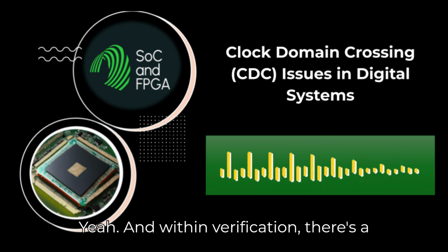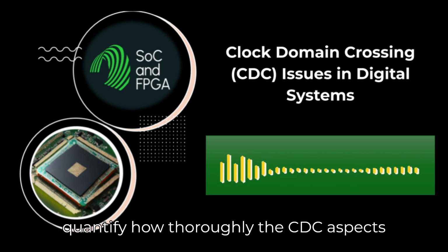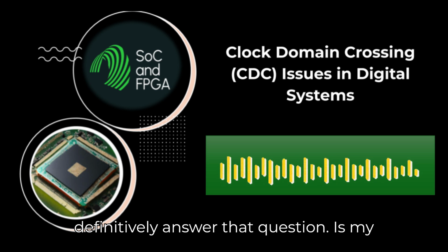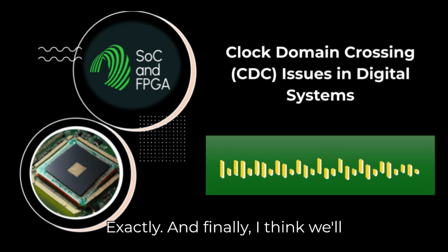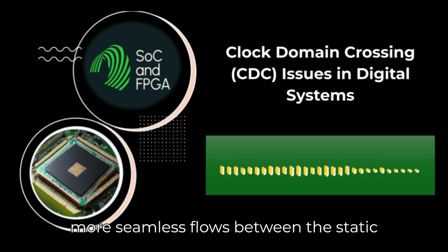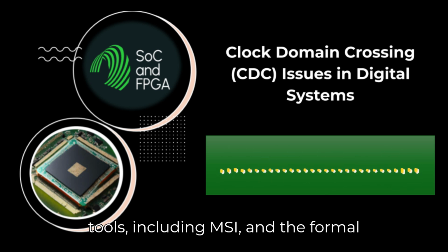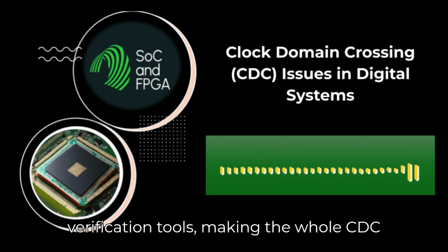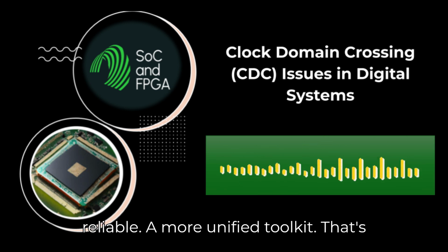And within verification, there's a push for more comprehensive coverage models, better metrics to actually quantify how thoroughly the CDC aspects have been verified, trying to definitively answer that question: is my CDC verification done? Moving beyond just bug hunting to proving coverage. Exactly. And finally, I think we'll continue to see tighter tool integration, more seamless flows between the static analysis tools, the dynamic simulation tools, including MSI, and the formal verification tools, making the whole CDC sign-off process smoother and more reliable. A more unified toolkit.